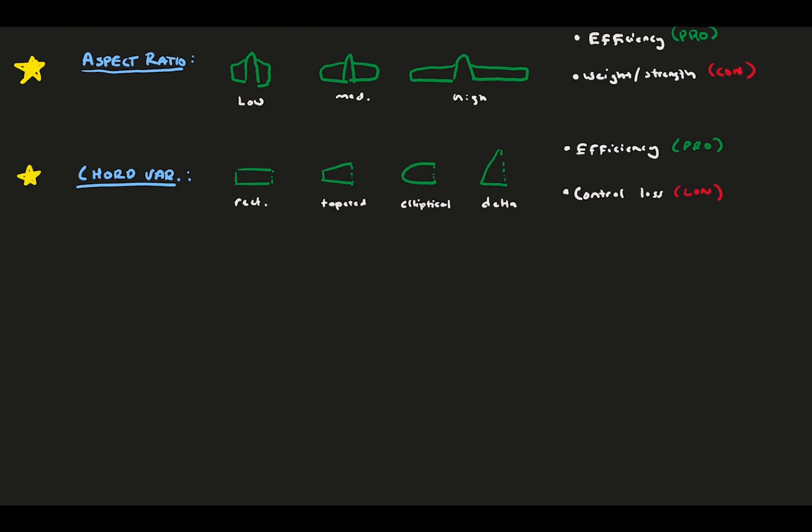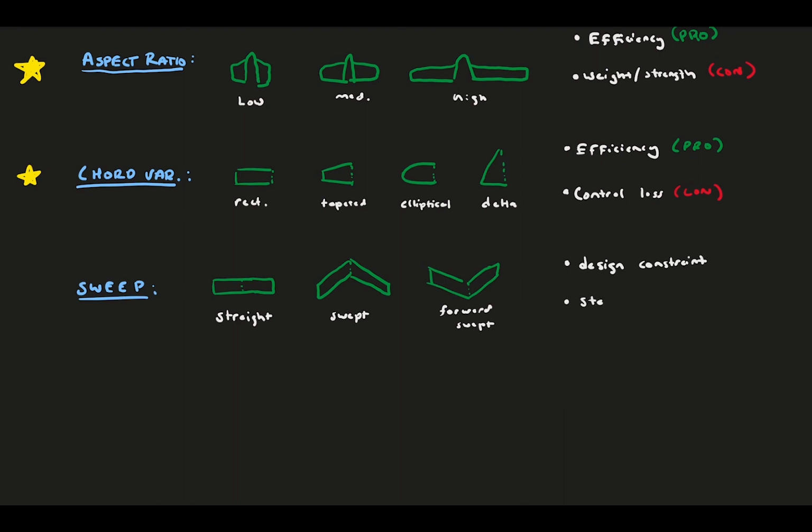The wing sweep, which is how the wings are angled from a top-down perspective, is also common to vary in modern aircraft. This helps in case you have to mount your wing root at a non-ideal location on the fuselage and want to alter your true position of the lift. Also, the sweep impacts flight stability.